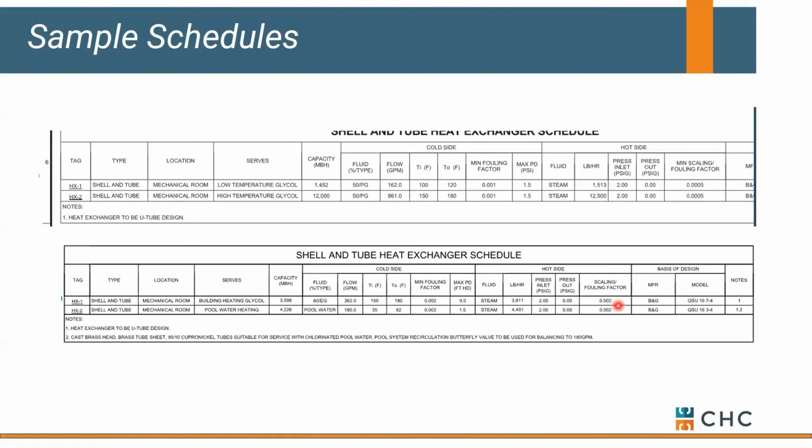That's off our charts as far as fouling factor goes. So we might be 250% total surface area. Drives you into some very large heat exchangers. So just be careful when you're scheduling. Make sure that your fouling factor is accurate because it has a big impact on how much surface you actually need.